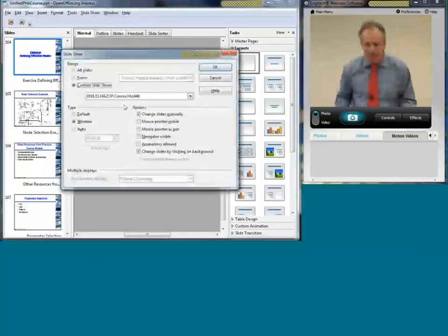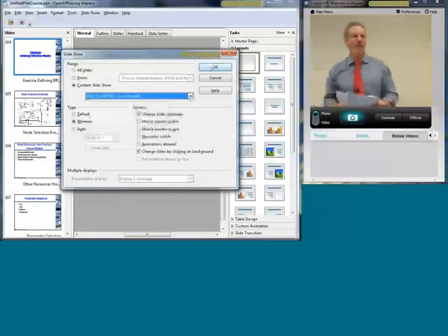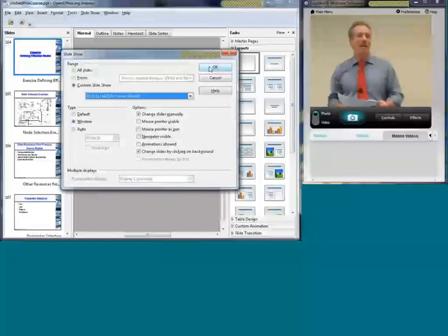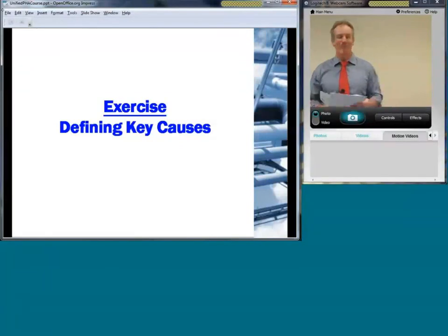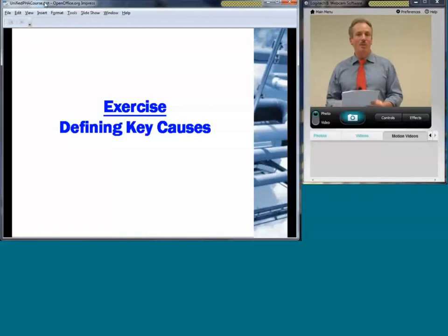All right. So this is the exercise we're doing on key causes. All of you who are tuned into the webcast have a physical copy of that small P&ID. And so what I'd like to do is hold your hand through the little workshop and define some causes here. All right. So node 1 is D906 in the level control valve. So let's talk about some no flow items. What sort of things would you look at as a team for no flow?